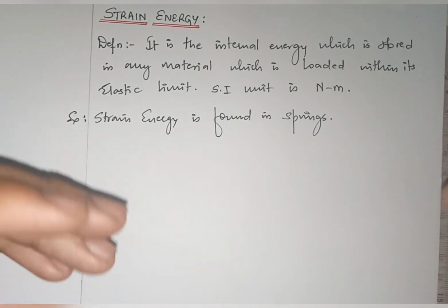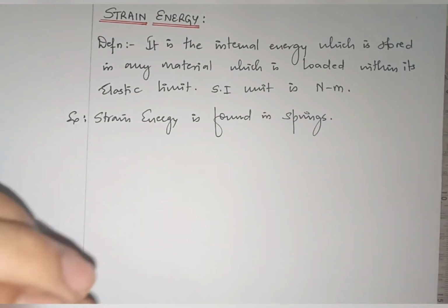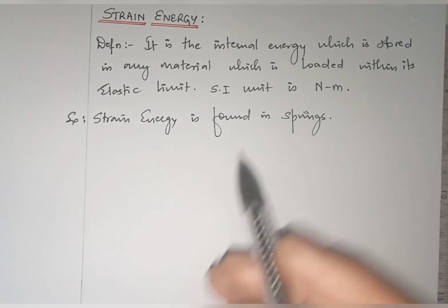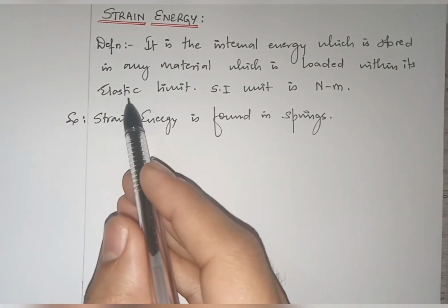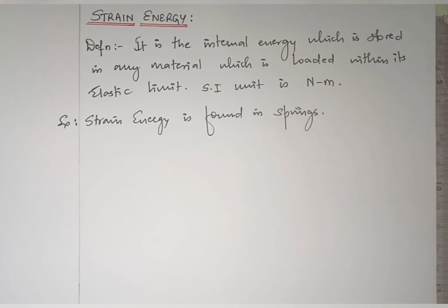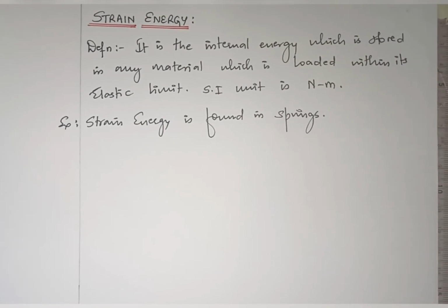Like this you can take any material, but the important condition here is the loading should be within the elastic limit. If you load more than that, then the material goes into the plastic stage and the deformation will not be entirely recovered, right? So that is the definition of strain energy.